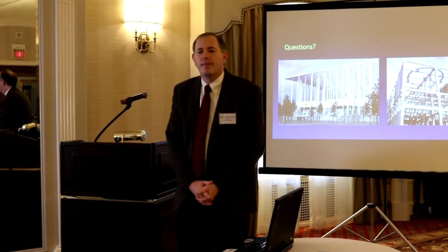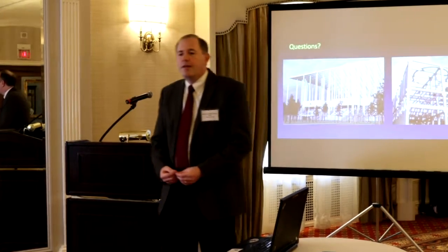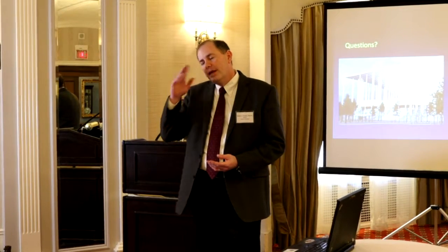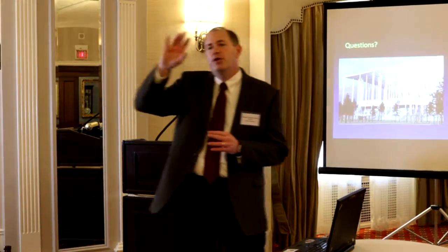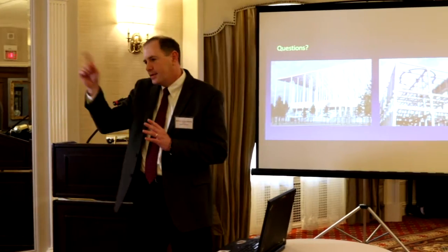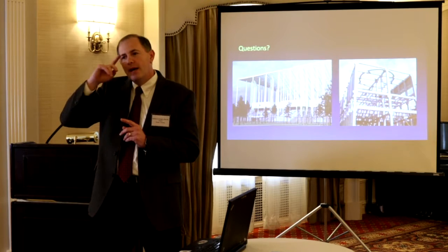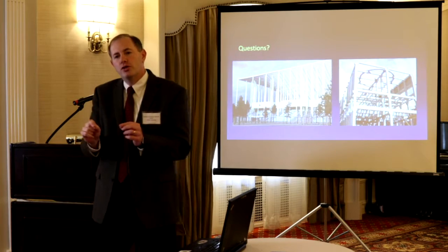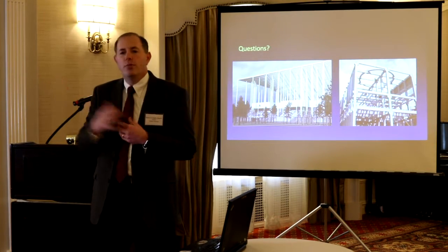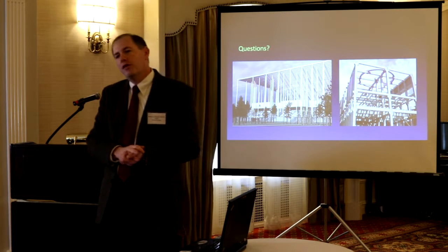Robert, do you need more research to find more findings on this? Yes, we definitely need more research on the sustained load effect. I'd like to take the same column and sustain it at different loads, say 10, 30, 40 percent, because I believe that will show us how much the sustained load matters. The lower my load level, obviously the less is happening. I believe it will show the 1.0 is going to work beautifully, and that we can predict them all the way up essentially to final failure.